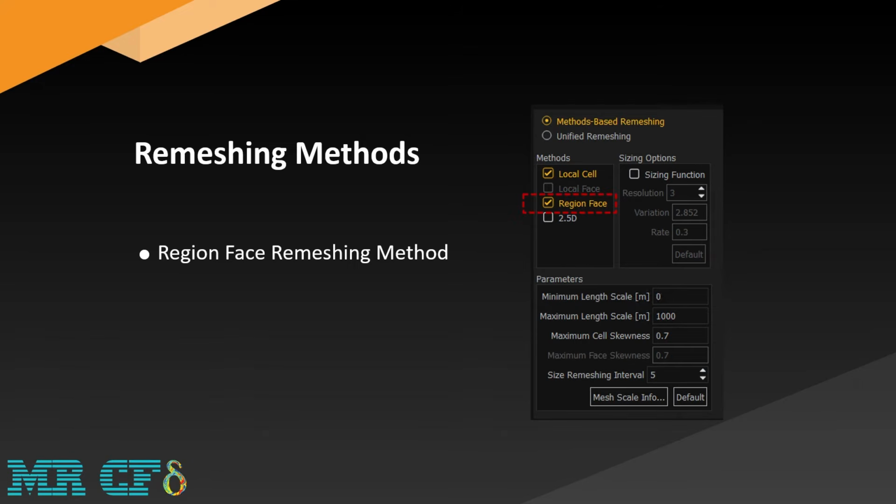In general, the face region method can only be used in cell regions containing triangular cells in 2-dimensional mode or tetrahedral cells in 3D mode.